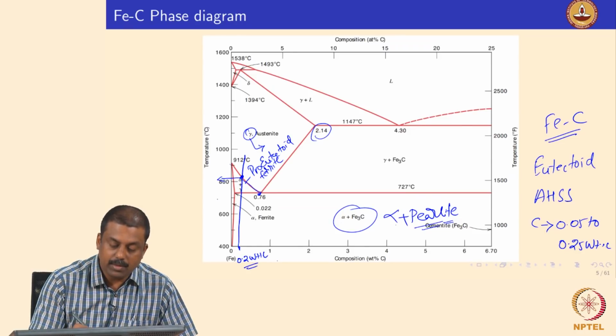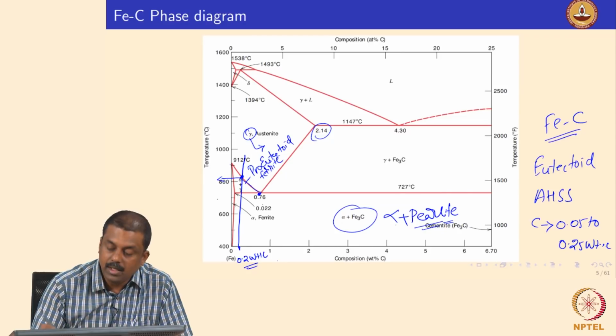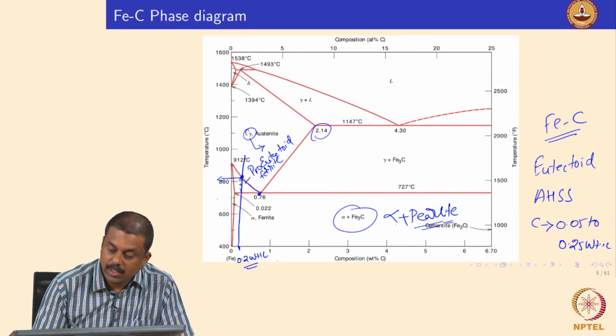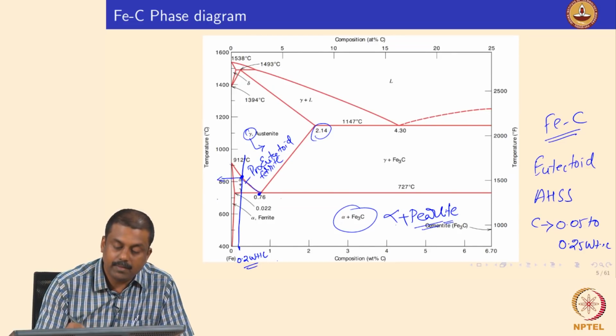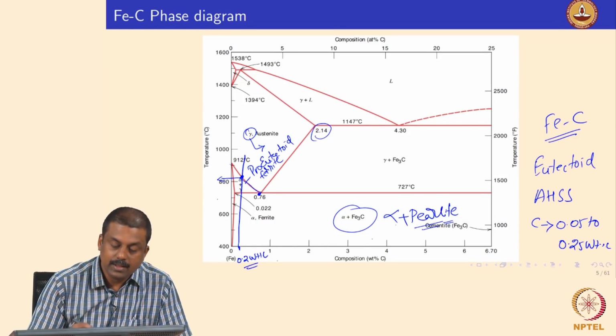And subsequently, the moment the carbon concentration of austenite reaches the eutectoid carbon concentration, the remaining austenite would transform into pearlite. Okay. So, if you are cooling steel containing 0.2 weight% carbon, you may have a mixture of pro-eutectoid ferrite and pearlite, right.